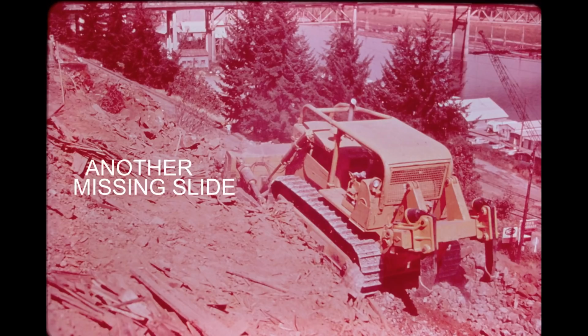A spoke-type sprocket is used on the TD25B, TD9B, and the 150 loader. The 25B sprocket also incorporates a 3-tooth segment, indicated in white, which, as on the 25C, allows easy removal of the pinion shaft. The sprockets on these machines are splined to the final drive carrier. The sprockets on all other units are bolted to the carrier.